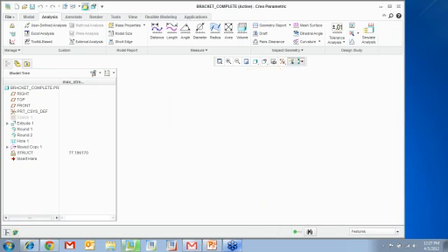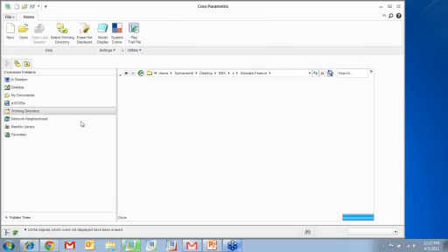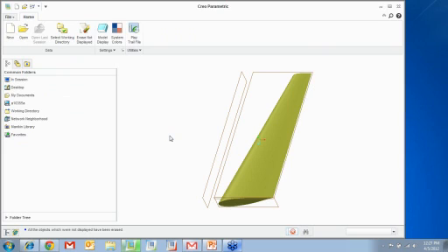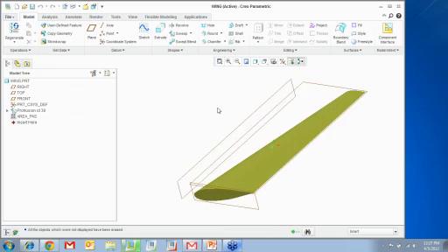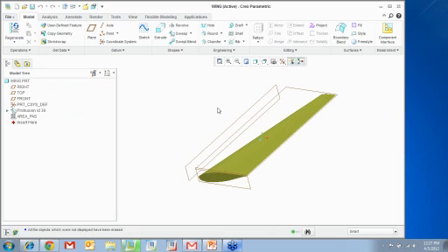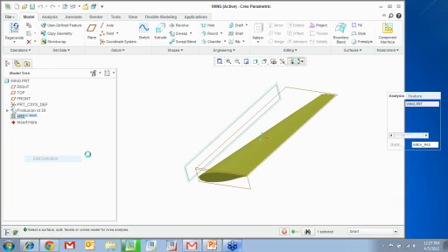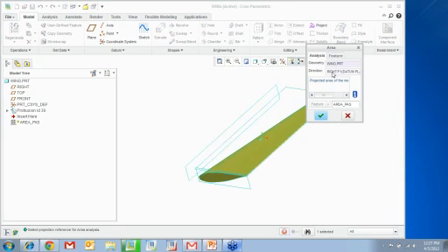All right. So next, after this, what we are going to talk about is something called an Excel analysis. Okay. In an Excel analysis, I'm going to use a wing part. All right. And I'm going to show you, when I change the angle of attack, what is going to be the lift force acting on this. Okay, so I have an Excel sheet done where I'm going to show you how to use that particular Excel sheet. So here I have area measured, so area of this part projected onto this plane.